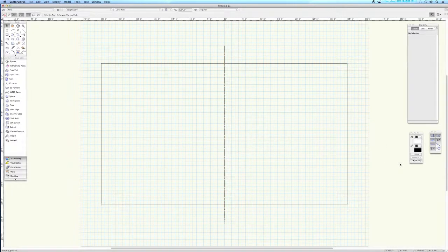The other thing that I want to point out on the attributes palette, you can see here that the line weight is 1. That's 1 mil. I'm going to change that. I have preset all these different line weights, and I'm going to change it to a 5. For my printers, I find that a 5 mil line weight is a good lightweight line.